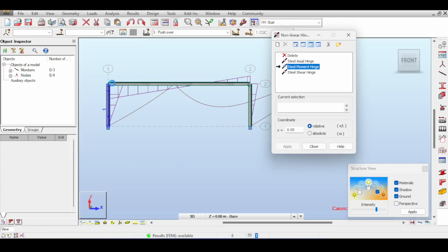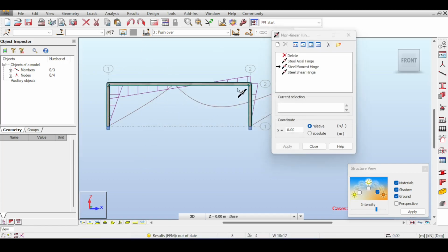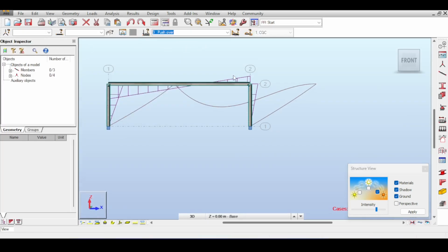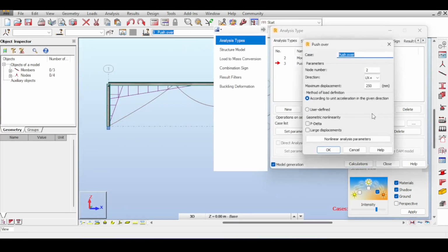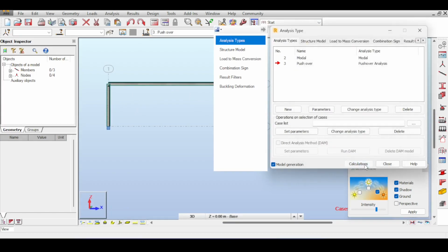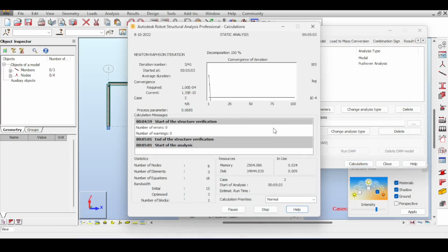I want to see what happens if I force all hinges to yield, which will make this a house of cards. Because if this yields and this yields and this yields and this yields, then all those hinges yield, which will create a house of cards effect, which will be unstable. So, I will add a ridiculously big displacement in the pushover just to test the theory here. So 500, okay. I just want to see if it actually feels the instability or not. I'm really surprised if it does.